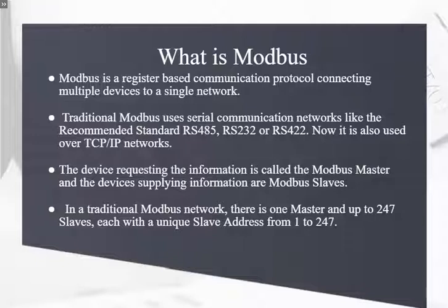In order for the client to know which device it's communicating to, the serial devices in serial networks are given an ID number between 1 and 247. TCP servers are given an IP address. They are sometimes referred to as a master or a slave. The master is the same thing as the client, while the slave is the same thing as the server.